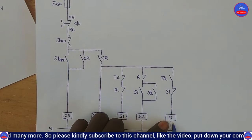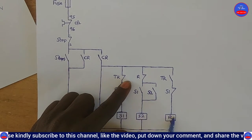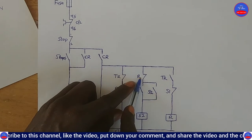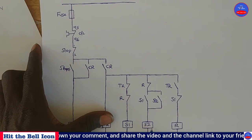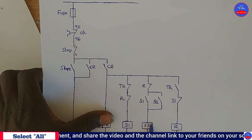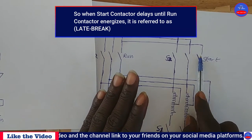When the R1, the run contactor, energizes, it is now going to open this contact, because this contact is on the run contactor. So when this side energizes, it's going to open this side, and then the S2 will go off. The S2 is the start contactor. So when this start contactor goes off, or de-energizes, it is going to open this side. All right, you see that?